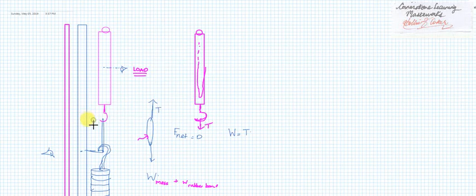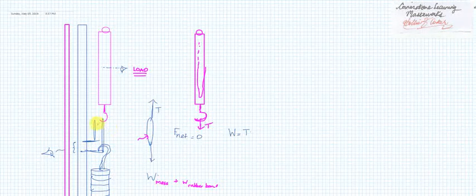Original length, it might be like this. And the original length, so that this part here is your extension, right? You must have a diagram showing that. You must have no load, that was the length. When you add the load, this is what it is. It gets a little longer, right? And you must say hang the ruler plumb. So this is how you measure the extension.